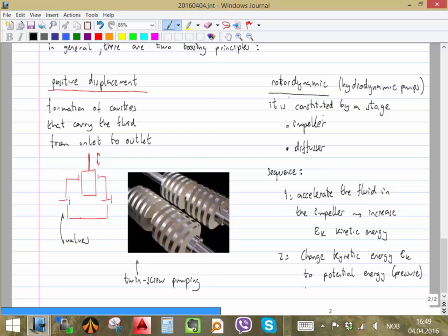Okay, I don't have space here, but if you have point 1 and you have a diffuser, point 2, the pressure in 2 should be greater than pressure in 1, and the velocity in 2 should be less than velocity in 1, just because of the expansion effect. And remember, this expansion, we have to do it as smooth as possible, because if we do it too abruptly, then the fluid is going to detach from the walls and it's going to create turbulence, it's going to create swirls, and that's going to give us a lot of problems.